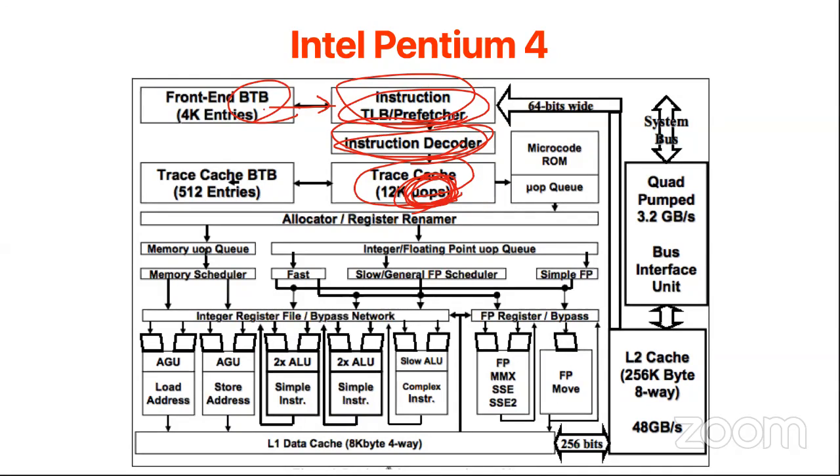On the other hand, if you just learn from the textbook, you will feel like CISC design is not efficient. However, how they really make it efficient is that in their front end they have the decoder. They modify the instruction decoder to create RISC-like instructions internally.